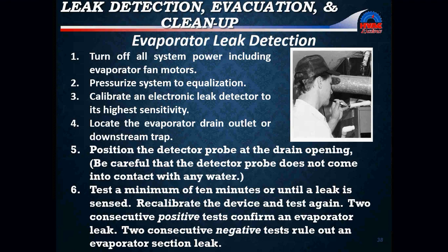Locate the evaporator drain outlet or downstream trap. Position the detector probe at the drain opening. Be careful that the detector probe does not come in contact with any water, though. If you put any water on the sensor, you just botched your entire effort to find the leak.